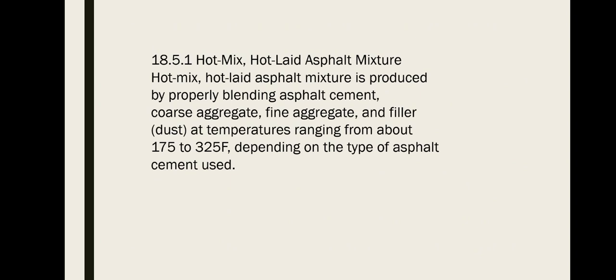Hot laid asphalt mixture is produced by properly blending asphalt cement, coarse aggregate, fine aggregate, and filler dust at temperatures ranging from about 175 to 350 Fahrenheit, depending on the type of asphalt cement used.